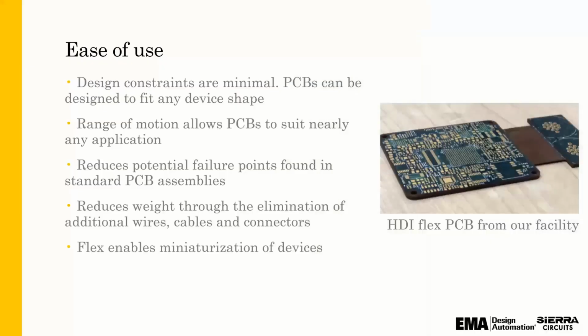So in terms of how to use and the ease of use and the benefits, I think the key point is the reduction of failures in the PCB. Every solder joint is a source of failure, as the saying goes, and it's true. So in your connectors, let's say, you could possibly eliminate some connectors and use rigid Flex instead, and that would eliminate potential failure points.